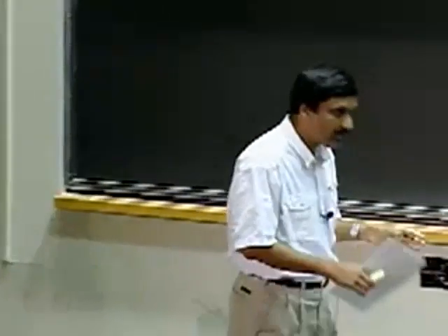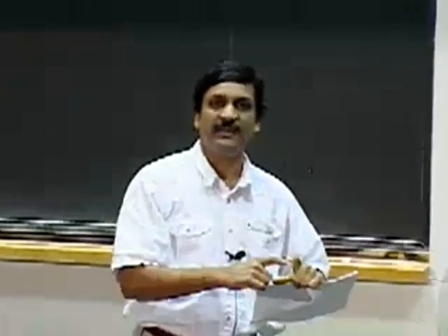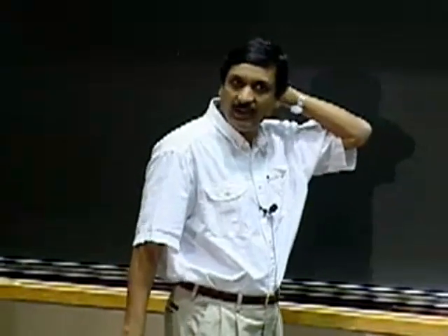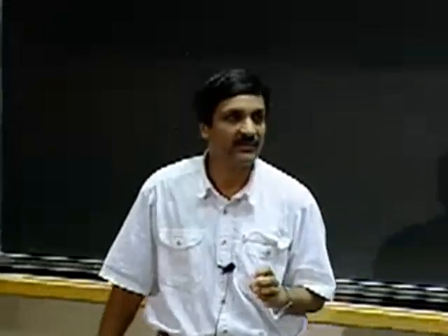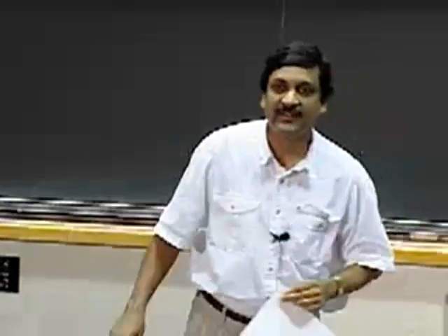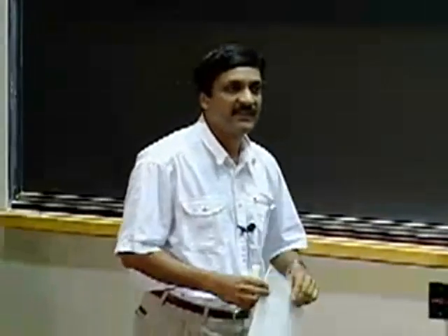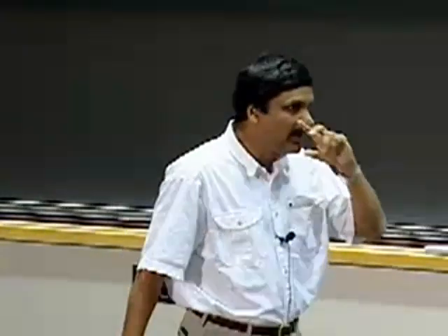And you'll see towards the end what I mean by two independent capacitors. If I have two capacitors in parallel, they can be represented as a single equivalent capacitor, so that doesn't count. It has to be two independent energy storage elements, and resistors and voltage sources and so on. And what we end up getting is what is called second order dynamics. Much as first order circuits were represented using first order differential equations, this kind you end up getting second order differential equations.